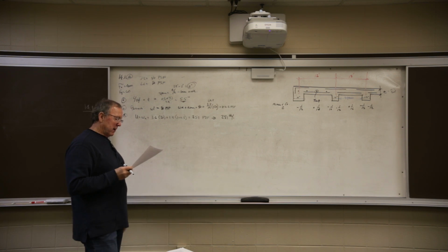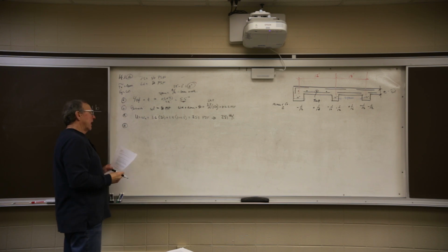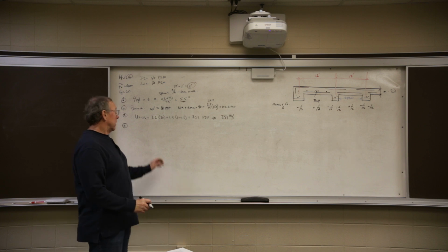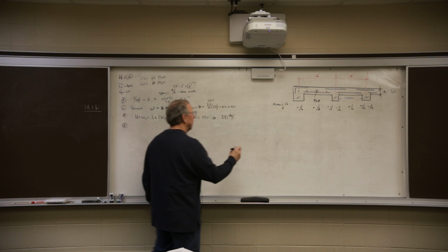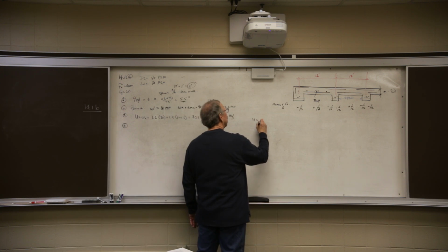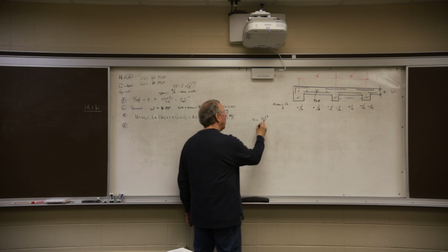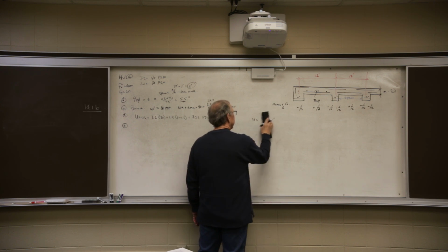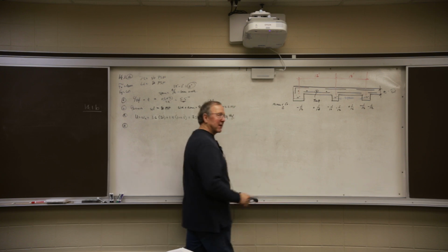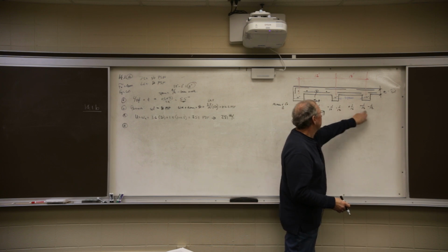Now, here's a diversion, letter D. Okay, last time we ended up with an equation that looks like this: M equals little w L squared over 8. I told you the 1/8 was the moment factor. In this, we don't have 1/8. You don't see an 8 anywhere, just minus 12 and plus minus.